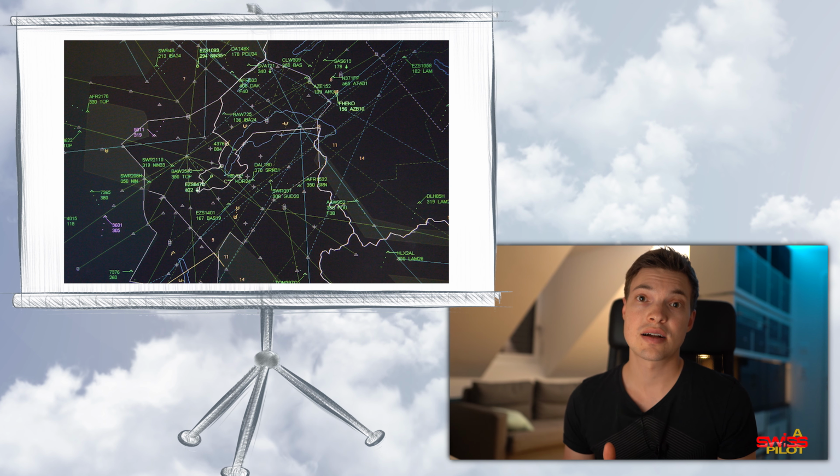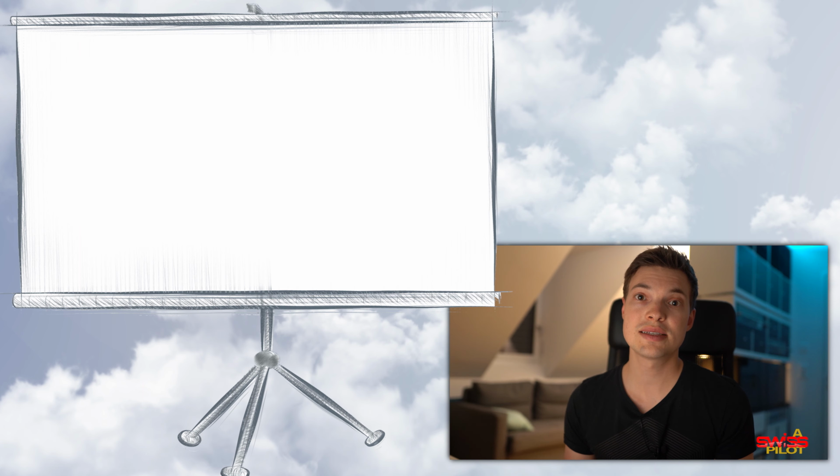There are actually two types of mode S transponders, those that just serve the basic so-called elementary surveillance functionalities. You could maybe think of it as basic mode S transponders. And then there's those who also downlink additional information, that's for example your aircraft speed or the selected altitude that you have selected in your autopilot window, for example. This will then be called enhanced surveillance. Now, it's important to know that mode S isn't yet the same thing as ADS-B, not even with the enhanced surveillance functionality yet.